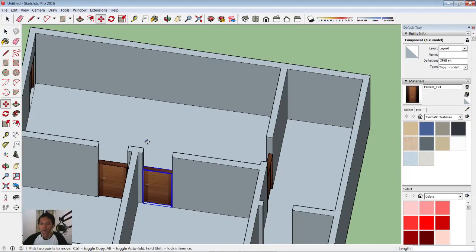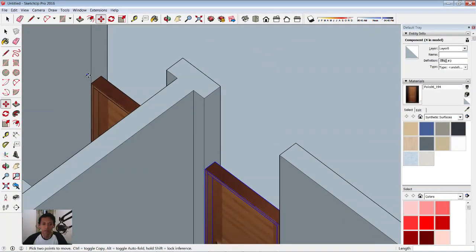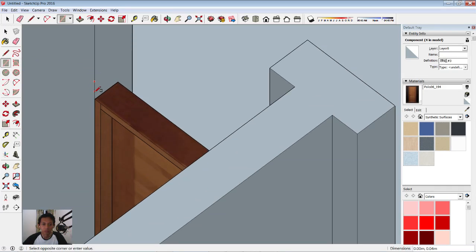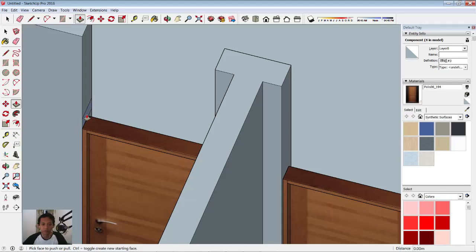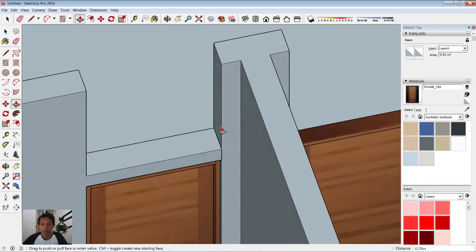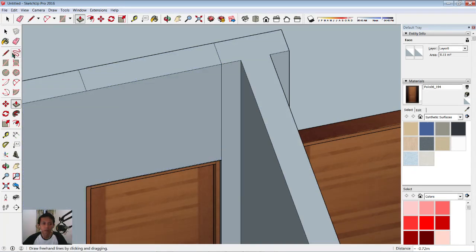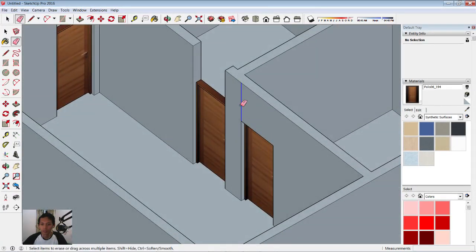Okay. Now I will create a rectangle in here. Okay, use a rectangle command, create a rectangle in here. And then you can extrude this rectangle object into this point and extrude to the top here. Use erase tools to erase this line object. And we erase in here.